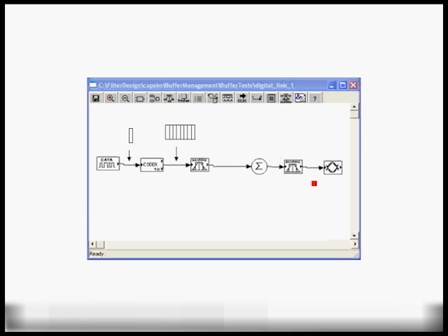At the receiver, we have a square root Nyquist filter, and we look at the eye diagram over here. So this is a case where we have multi-rate signal processing. For every input bit, we generate 8 output samples for the coder, which are actually impulses into the square root Nyquist filter. We have the impulse responses superposition over here. And overall, we have a Nyquist pulse shaping, and we'll look at the eye diagram.